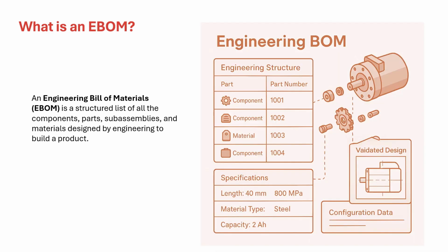Whereas an engineering BOM defines all items, parts, components, sub-assemblies, and assemblies in the product, designed by an engineer, that are necessary to build the finished product or the product line. These parts will include software parts, electrical parts, electronics, mechanical parts, and documents. Whereas a design BOM does not include documents or software parts. An engineering BOM may also include non-geometric parts such as sealants, lubricants, colored parts, or similar parts.